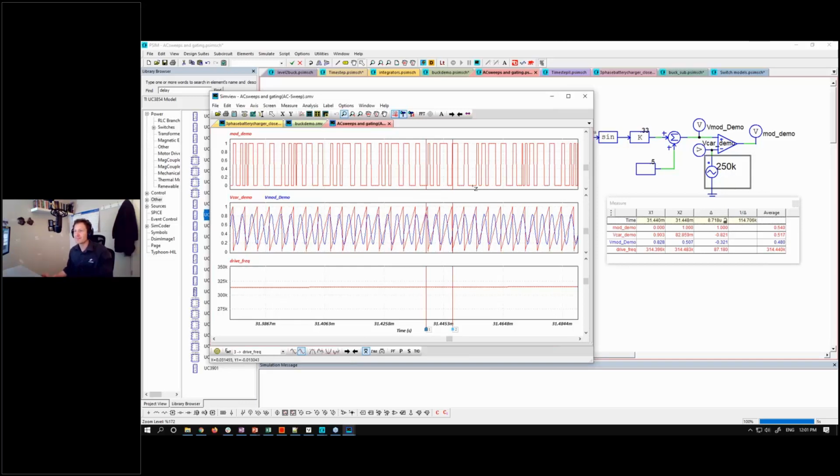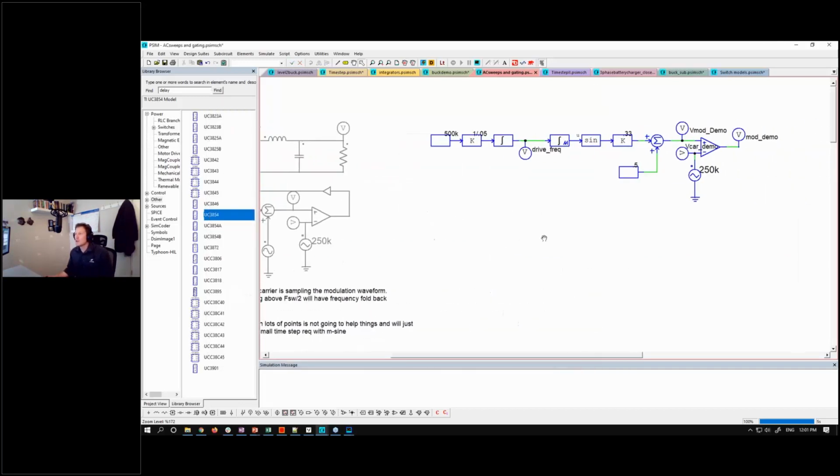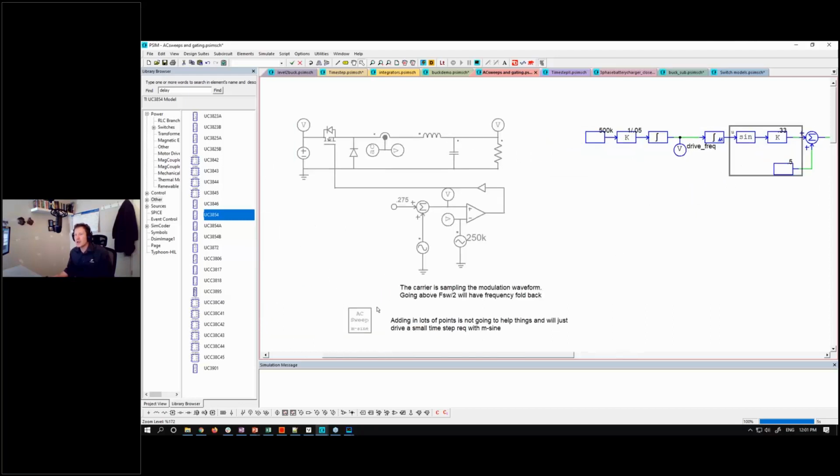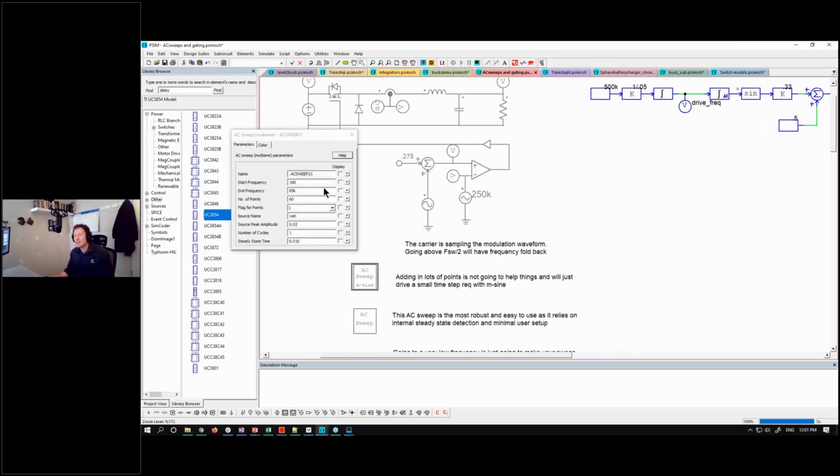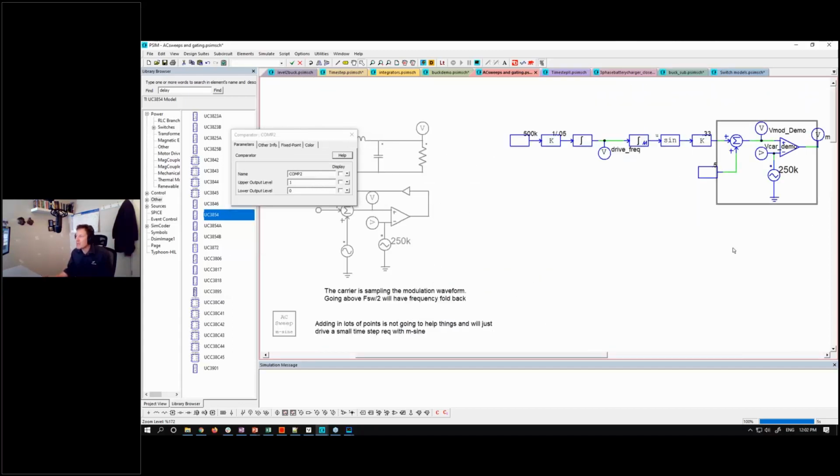It just doesn't make any sense. So when you're running a frequency sweep, you need to understand what the engine is doing, and that is injecting points or target frequencies. They're being compared with the carrier, so trying to go to too high a frequency just doesn't work. That's where you start seeing the noise at the high frequency range.